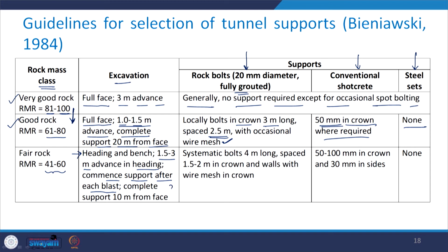So, complete support should be 10 meter from the face. In this case, if you have the rock bolts, systematic bolts 4-meter long should be provided, which should be spaced 1.5 to 2 meter in crown and walls with wire mesh in crown. That is also needed here.